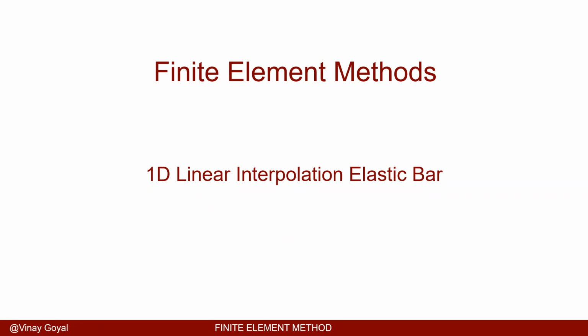So we're going to be extending the ideas of approximation methods for the strong form Galerkin, weak form Galerkin, and Rayleigh Ritz. Finally, we're going to be applying finite elements. Now, when we studied the spring elements and the truss elements, they didn't require differential equations, and that's what makes it different in the sense that we're now really applying the idea of approximating solution over a domain and then formulating the finite element method. In my book, I basically covered several chapters. Now I'll be covering chapters 4 and 5.